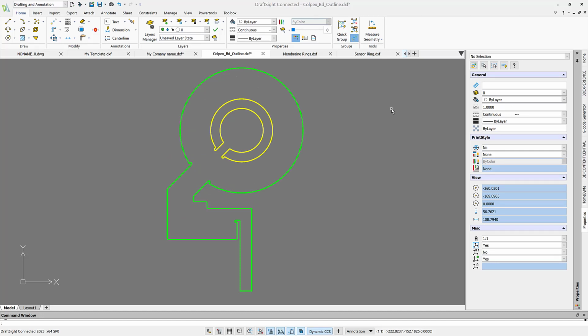Here's this board outline. Now, if you had to create that inside your PCB layout software, no matter what it is, Cadence, Zuken, Altium, or PADS, you will have a very hard time because it's just not designed to be able to handle this complex board outline. But here in green is the board outline, and in here is even a cutout that we might have inside our board so we don't place anything.